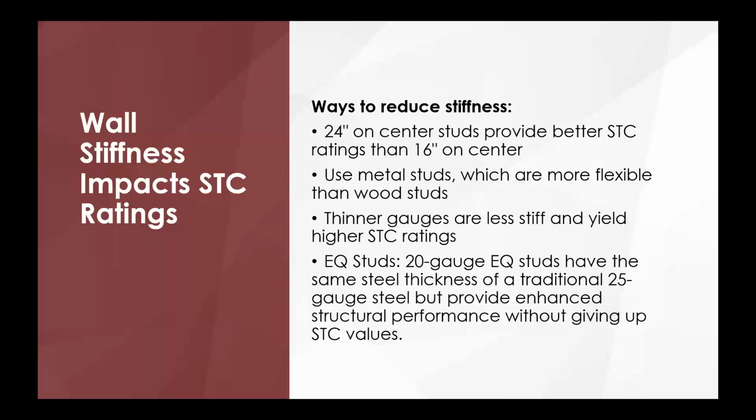Now, in my opinion, there is a sweet spot in there. It's in the EQ 20 gauge studs, because EQ studs have generally the same steel thickness as the traditional 25 gauge steel studs. So you get the benefit of improved structural performance without giving up the STC values.